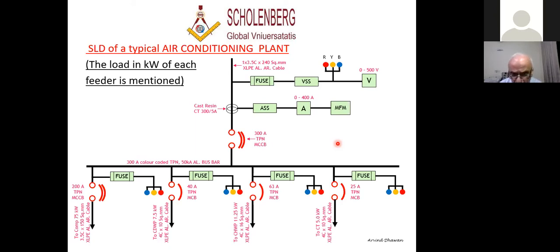After the tender is awarded, the consultant or the engineer will again say this drawing is fit for construction. Tender drawing and fit for construction drawing may be different because between the initial floating of the tender and the construction, a lot of discussions take place.